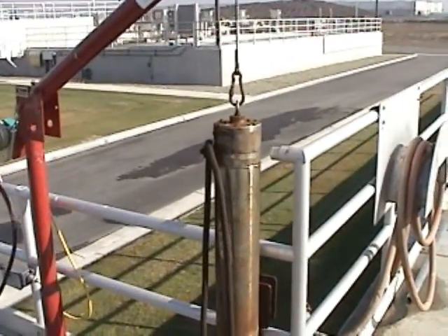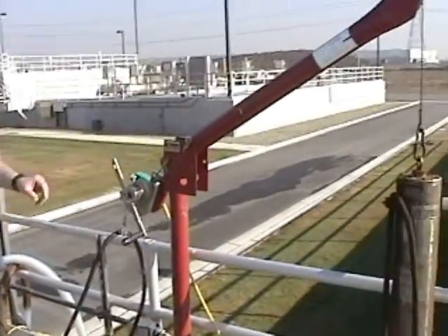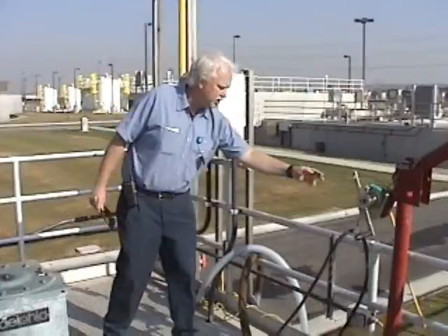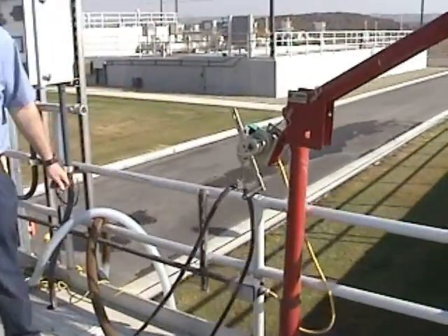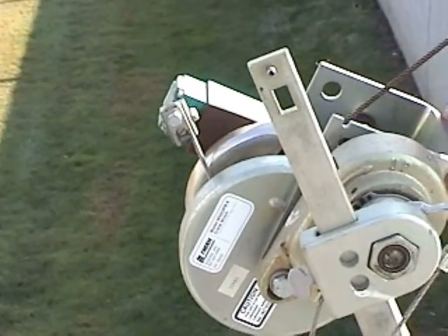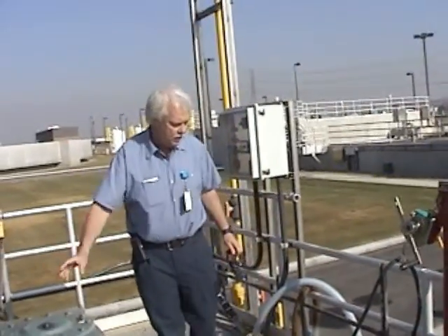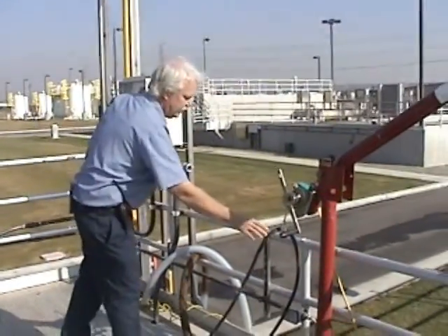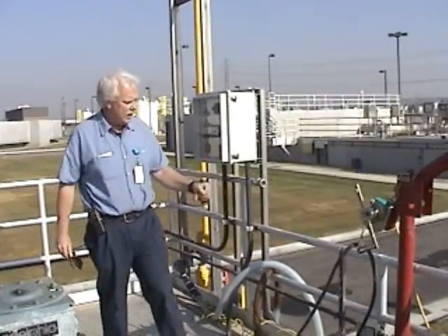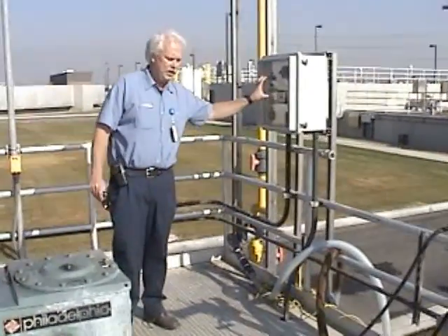Getting this in and out of this tank involves opening this hatch right here and then dropping it with this little crane into the water. It's wired in such a way through this switch that you cannot start it. You have to turn this Philadelphia mixer off to start the water champ, and the reason is they share the same vault. If you have the water champ in this vault and you turn this on, the control cables, the power, the water champ itself can be dragged into this impeller. So our electricians wired it such that if you do drop the water champ, this has to be switched off. And it's done through this panel right here.